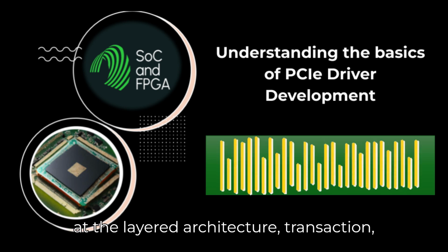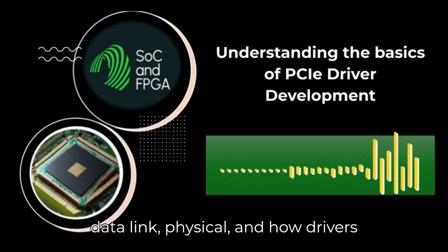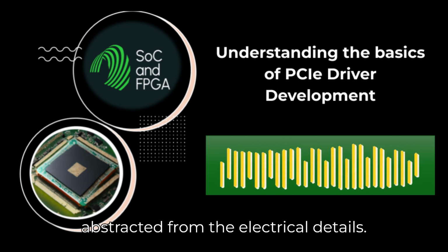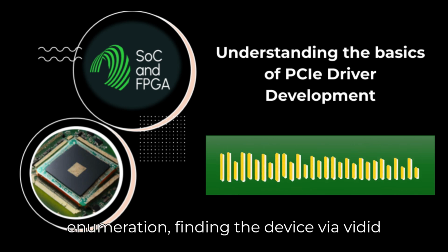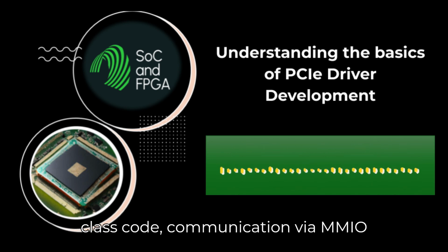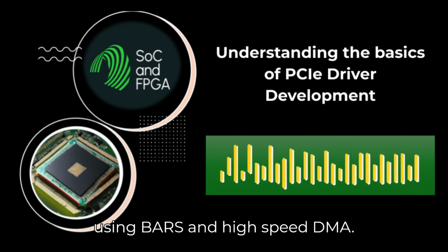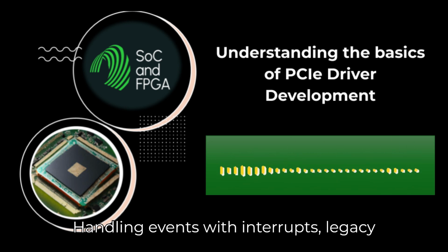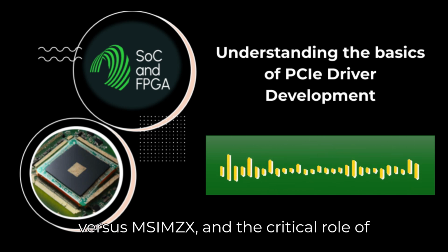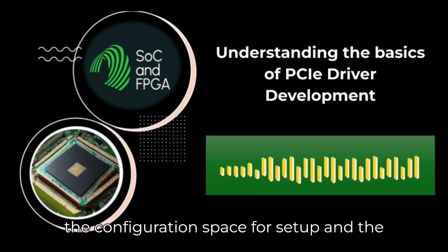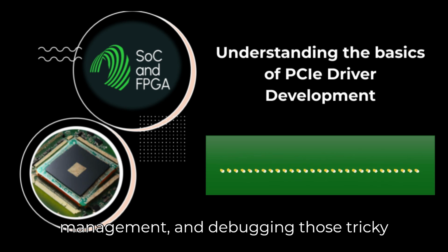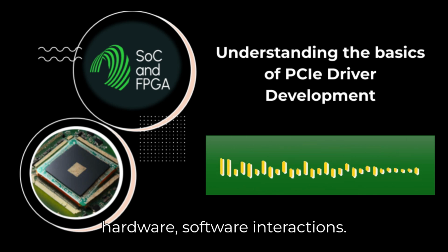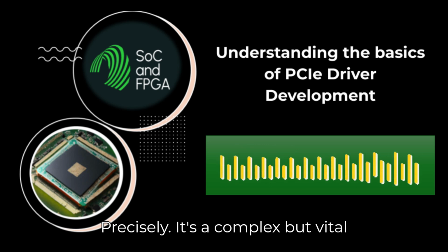We looked at the layered architecture: transaction, data link, physical, and how drivers mainly interact with the upper layers, abstracted from the electrical details. We covered key driver tasks: enumeration, finding the device via VID/DID and class code, communication via MMIO using BARs, and high-speed DMA, handling events with interrupts, legacy versus MSI-X, and the critical role of the configuration space for setup. And the challenges, like kernel mode, resource management, and debugging those tricky hardware-software interactions. Precisely. It's a complex but vital technology.